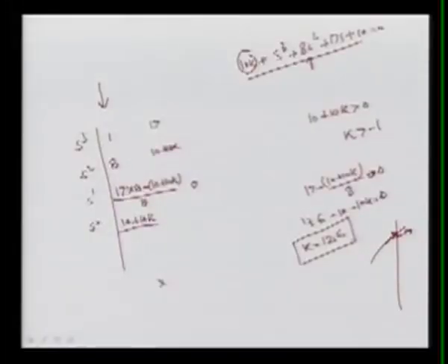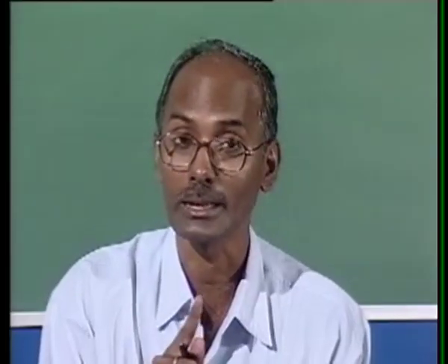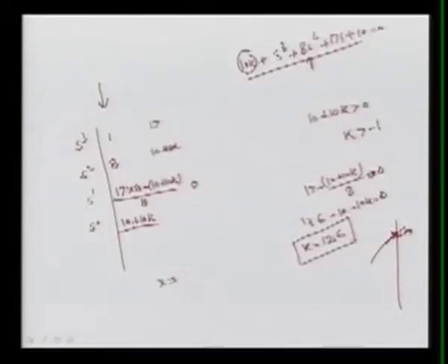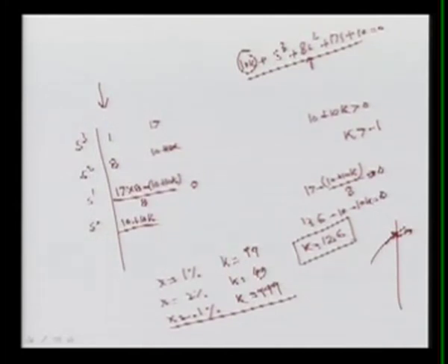But in the static case we saw for the same time constant, because it was not related to the time constant, the gain at that time. So for accuracy of 1%, we saw k was required to be 99. For 2%, we saw we require k of 49 gain, and for 0.1%, k was 999. Means if you are going for more accuracy, gain is more, but here it may change and it may cross this. For this k we can determine what will be the accuracy as well, no doubt.